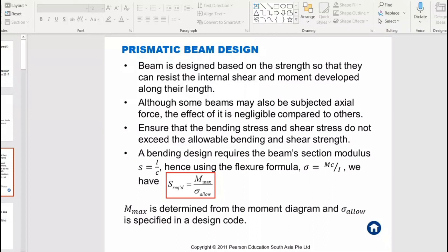That's what we did in the beginning of the class, like two or three classes before, when we found the strain due to pins and links and so on. Especially the required spacing of nails or bolts of a particular size is determined from the allowable shear force and shear flow, which is equal to VQ over I, calculated at points on the cross section where the fasteners are located. Right.